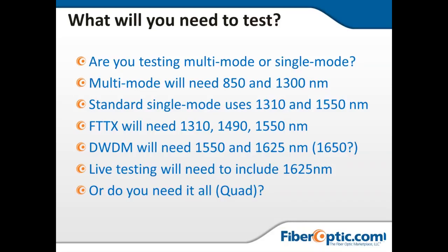In that scenario, a lot of times what we're looking for is that 1550 wavelength, and because of the distances of a lot of those, the 1310 has too much loss, so we typically have to bump up to something like a 1625 nanometer wavelength to get the distances. A DWDM system might be a core backbone for AT&T, Verizon, someone like that, where they need to get a lot of telephone calls and data transmissions over one single fiber.